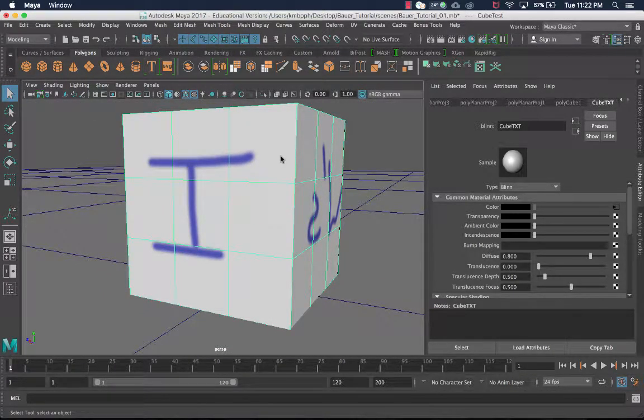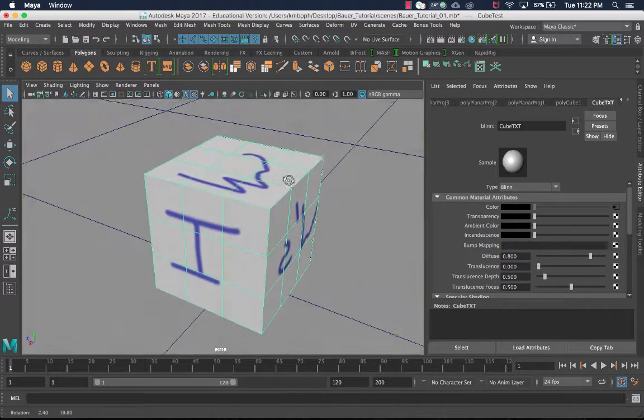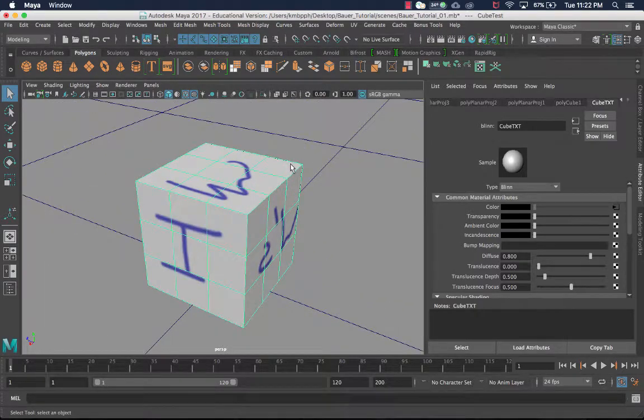That means you've been able to apply a file or a painted texture onto one of your objects in Maya. That is what we were hoping to do for the first part of this tutorial today, so I hope that worked out. If it didn't, there could be a bunch of different reasons why. You really just want to make sure that you're applying it to the correct shader. So you want to go into that blend that you had been using and then create a file and load up your image from there. That's important. You also want to make sure you have 6 turned on. If you're on 5, you won't see your textures. So if you have 6 on, you will. That could be another issue that's throwing you off here too.